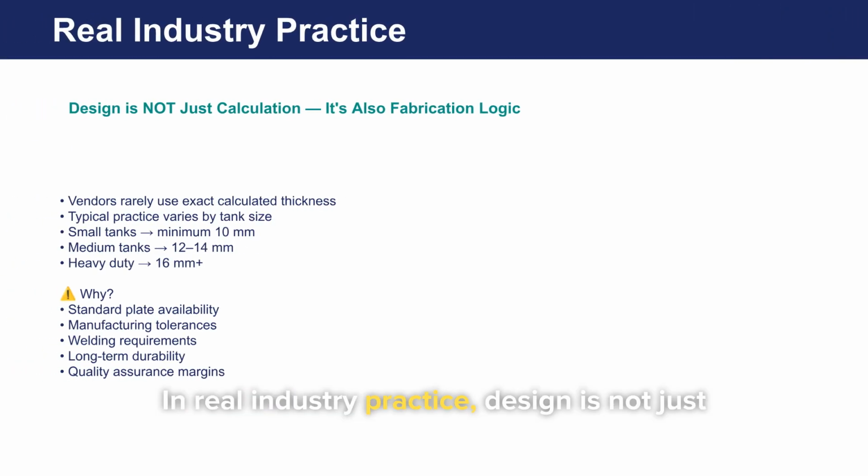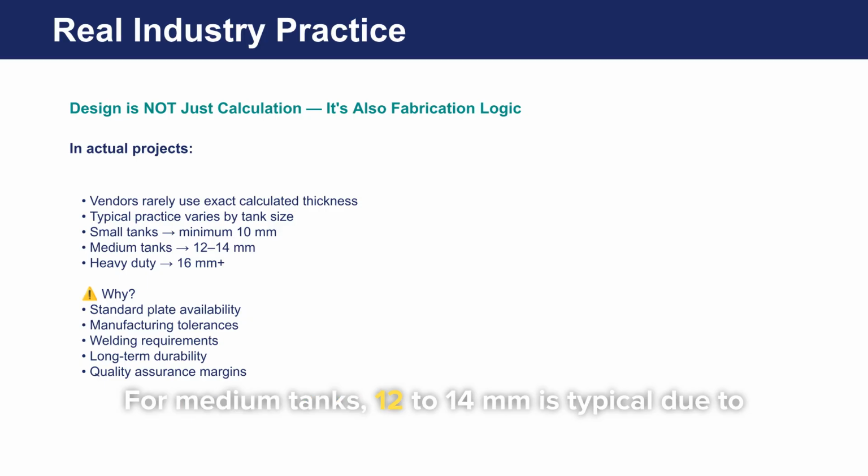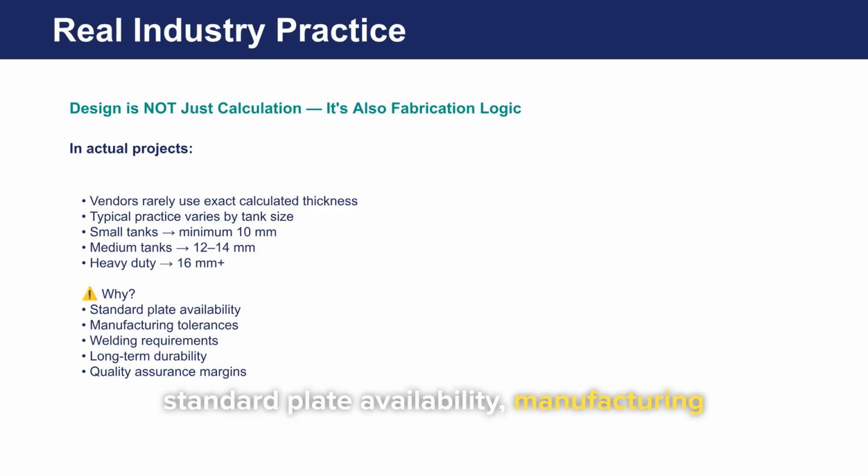In real industry practice, design is not just calculation. It involves fabrication logic. Vendors rarely use the exact calculated thickness. For medium tanks, 12 to 14 millimeters is typical due to standard plate availability, manufacturing tolerances, and long-term durability.